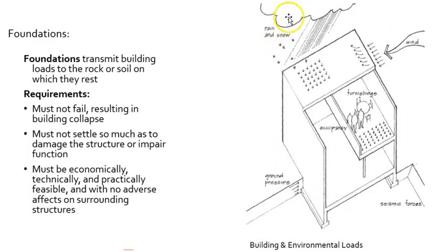So there are environmental loads, rain and snow, sitting on the roof, being transmitted down through the walls to that foundation. There are live loads inside, occupancy loads and furnishings. These are not parts of the building, but loads that come and go. They're referred to as live loads. The foundation must also transmit those to the earth below. And then the others, wind wouldn't really pertain to the part below ground, obviously, but ground pressure, either in the form of soil or water below grade, pushing on the foundation. So different loads that the foundation needs to accommodate.